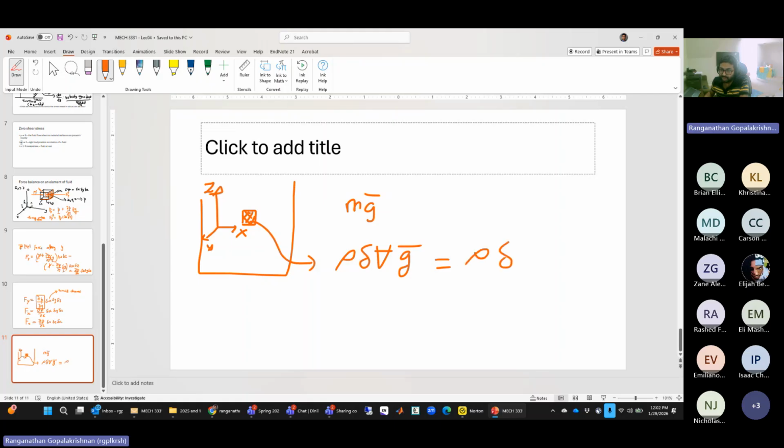And if we assume that g acts along the vertical, along the z direction, we'll write it as g, the scalar, multiplied by k with a negative sign, because g always acts down. According to the picture I've drawn, I have to add a negative sign to denote this is gravity. Remember, we are still dealing with this very tiny volume of fluid whose volume is delta V, so I'm going to write minus rho g delta x, delta y, delta z times k cap.